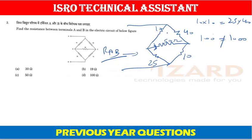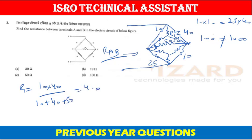Therefore, now we have to convert this delta into star, like this. Similarly, like this. To convert delta into star, suppose I say this is R1. Therefore, R1 is equal to 10 into 40 upon the sum of the total resistance of the delta, that is 10 plus 40 plus 50, which is 400 upon 100. Then this star resistance R1 is equal to 4 ohm.